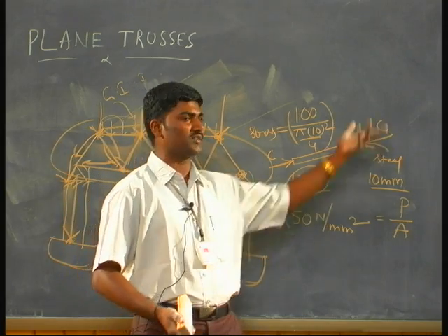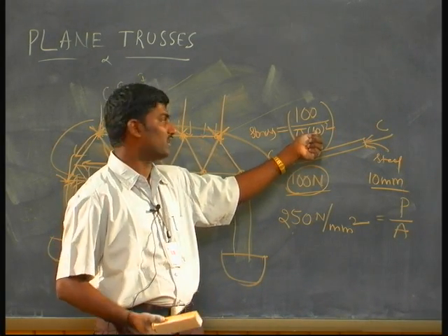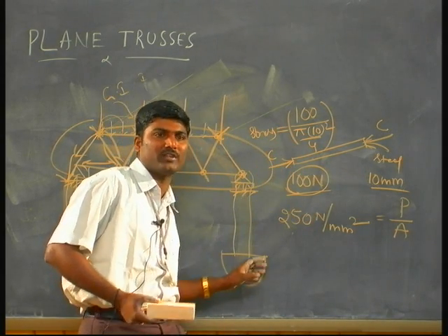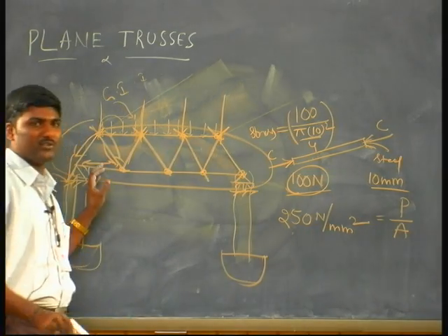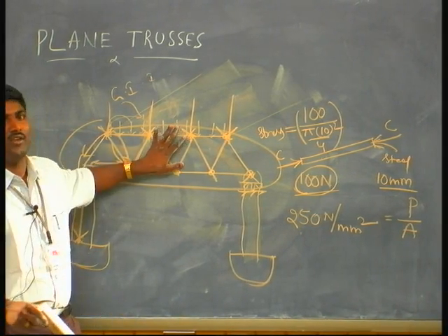So you increase the size. If you increase the size, you go for 12 mm, 14 mm, so that the stress will go down, it will fall below 250, so that you are safe. So that is the afterwards work. So what we deal with is only the analysis.